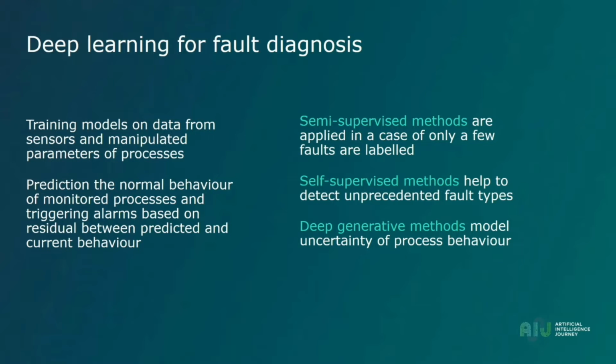There are also self-supervised methods where we can predict whether something is going to go wrong with the process or not based on the data. For instance, we can teach a predictive model that will predict faults in the future. If we see some deviations from the prediction, it means that the process has changed its behavior and potentially it might be a pre-emergency situation, and we can check it manually, or we can launch some more point-wise diagnostics.